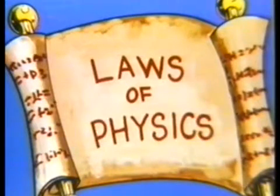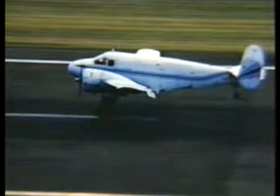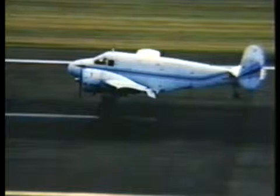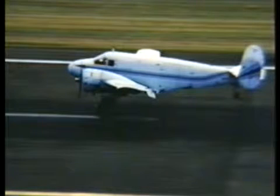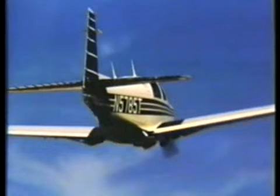Does an airplane stall at a lower airspeed when it weighs less? Sure it does. The lighter the airplane, the lower the stall speed. And what you want to do, of course, is touch down at or just above stall speed when you land. Let's go through the mechanics of a typical full stall landing to show you what I mean. First, let's say you just took off with a full load of people, baggage and fuel, realized you left something like your credit card back at the FBO, and immediately turned around to come back for it.